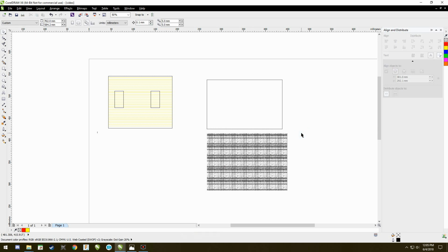A little difference with using a JPEG here versus doing the lines is this: with lines, I can tell the laser all to cut at one time. In this fashion on my laser, I have to cut this image first and then cut my box over top of it. Because the laser is a digital CNC type machine, I can set an origin and it will automatically go back to that same point every single time. So it's not a problem. If I were to cut this image and then load this image in secondly, or cut it right afterwards, I can cut them right back to one another. I just need to put the laser in 2 different modes.